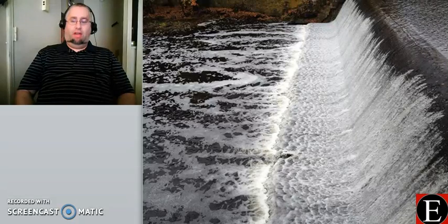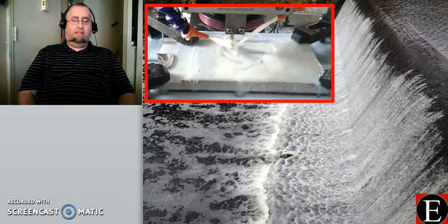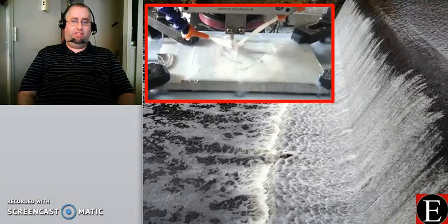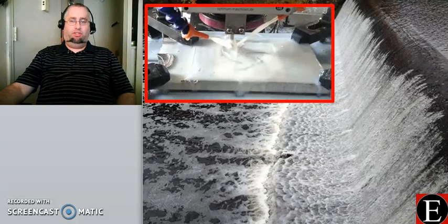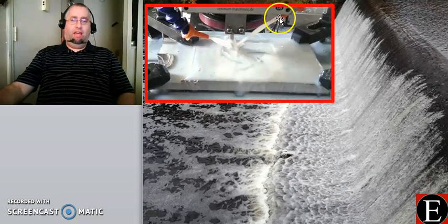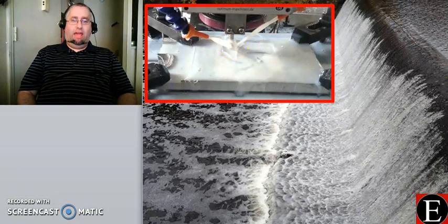Another application of hydraulic jumps is in flood cooling of machining applications. This is a milling application, and if you're milling at very high speeds and you're milling difficult to machine metals, you use a technique called flood cooling, where you essentially take the cooling fluid and just spray it as fast as possible at the workpiece and the tooling to keep everything cool as you're machining.